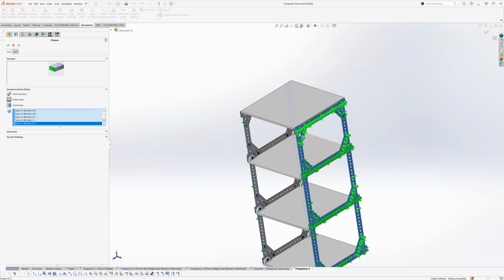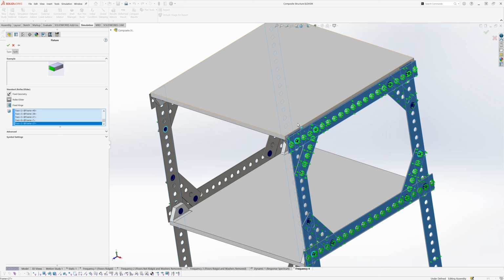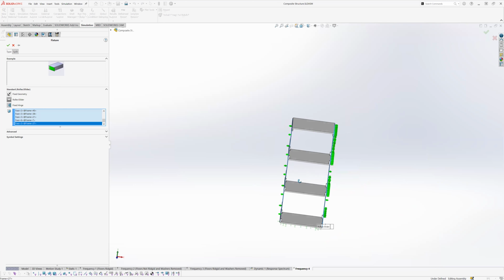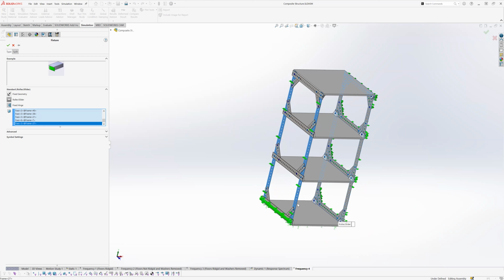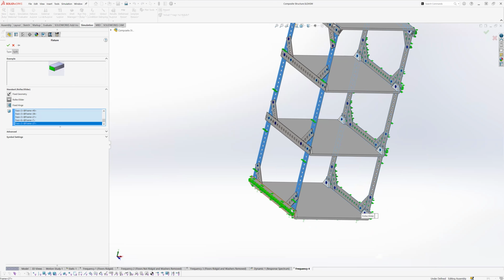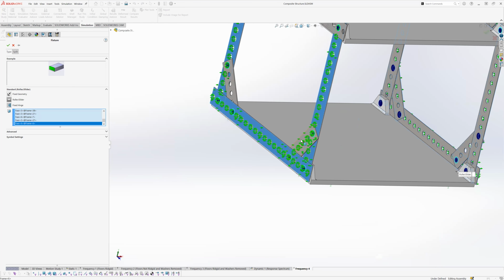Again, I don't have to do much with this face here because it's rigid. If it wasn't rigid, then I might consider doing something here because then it could still deflect. But since I've got the pin constraint here, and if it's constrained from translating in one point and the entire body is rigid, that should propagate everywhere. If we're getting results that don't make sense, we might have to go back and modify that. But when I ran this study, I say last week sometime, that was actually working fine. So unless we run into something new, that should be sufficient.